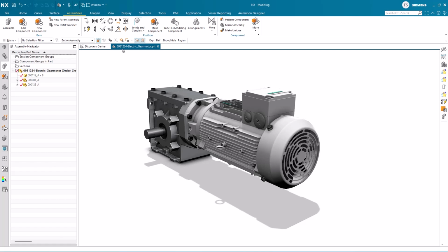The position group contains all the tools for creating the constraints that are needed to fully describe how the components are interacting with each other in the assembly. The most used would be the Fixed, Touch, and Align. The Auto Align option is great and a quick way of positioning most of your components.